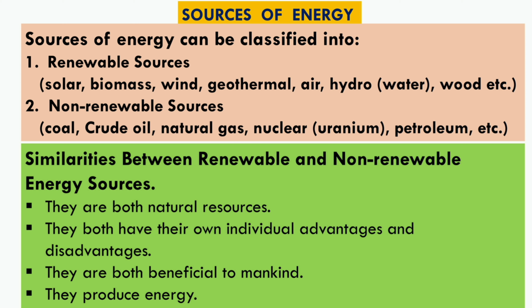Coming to the fuels, the main source of energy is the fuel. Fuels may be solid, liquid or gas, such as coal, oil and coal gas. Coal is available in huge quantities in almost all the industrialized countries. The coal is fired in the boiler, which produces steam. The steam so produced is utilized in steam engines or steam turbines coupled to the generators for generation of electrical power. The average calorific value of coal is 6700 calories per kg.